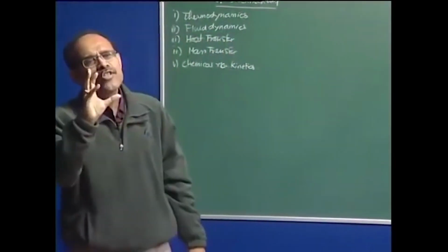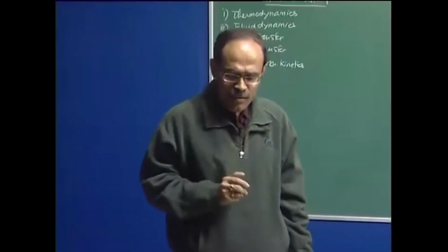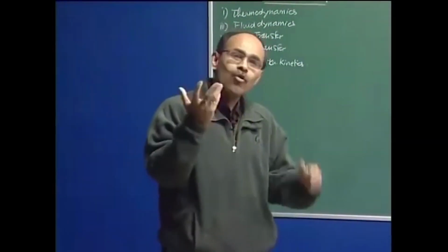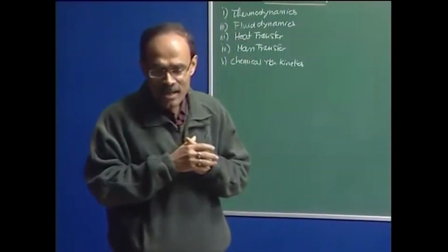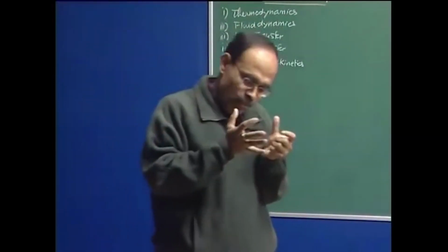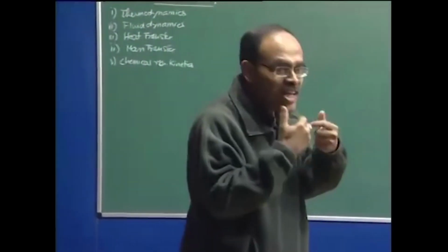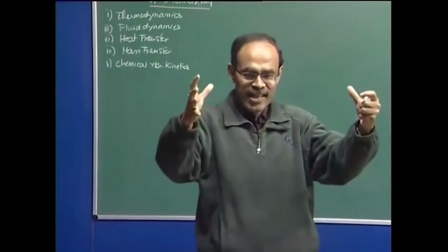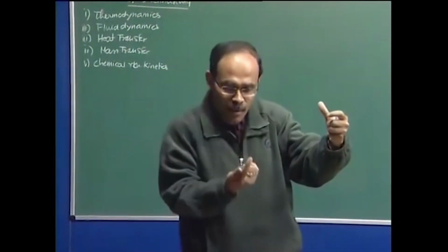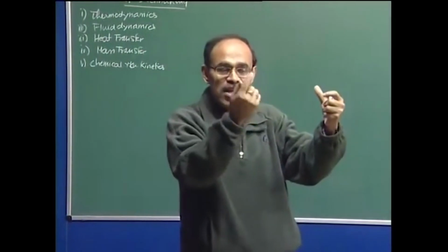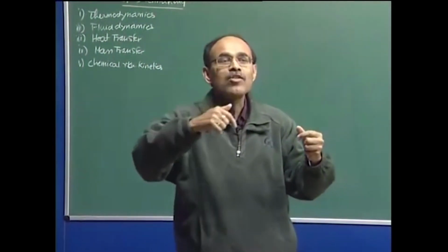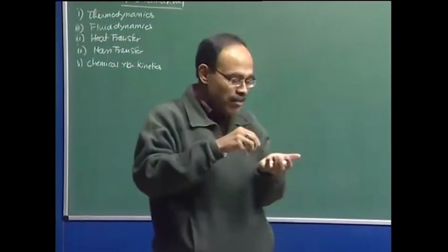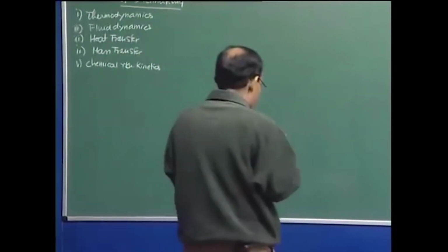Now, is the flow steady or unsteady? The next question that we ask is, depending on the process, the flow can either be steady or unsteady, because we know that it matters when the process is just started. For example, the ladle is sitting, metal is sitting in the ladle, and the moment I start to inject gas, from that moment onwards the velocity is going to change as a function of time. At some point of time the velocity will become constant. So, that looks something like this.